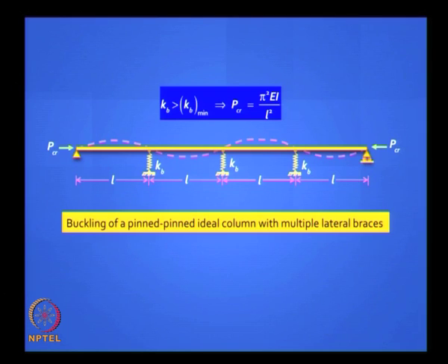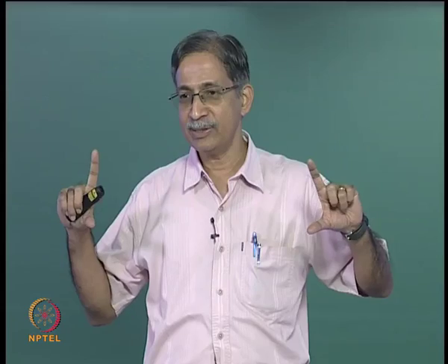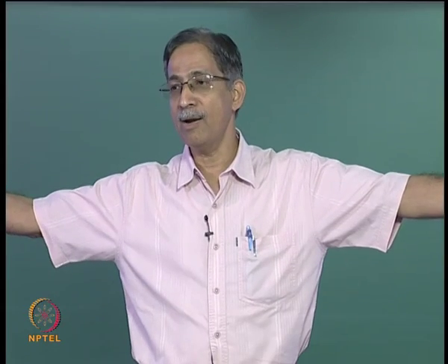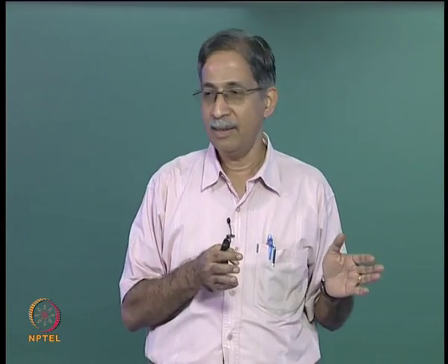So for practicing engineers, these kinds of fundamentals are very important, and especially when you have a very long column. You can work out the minimum bracing needed. It need not be infinite, but you have to provide appropriate stiffness to make a long column behave like a relatively short column to increase its capacity.